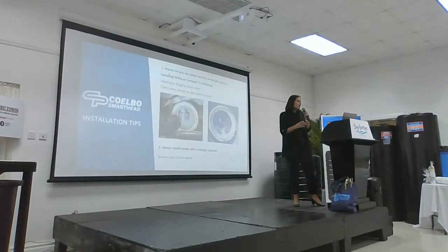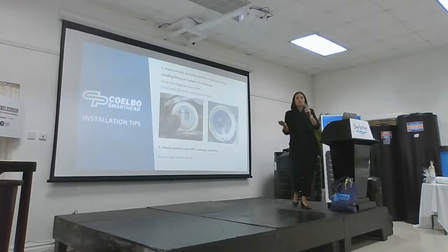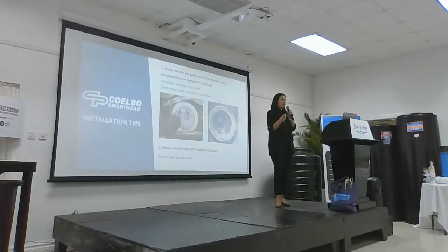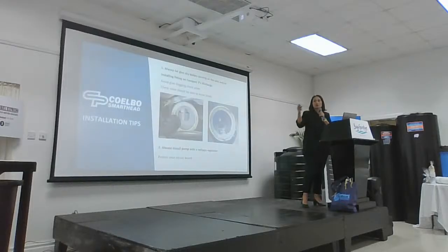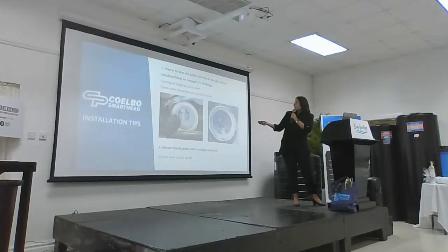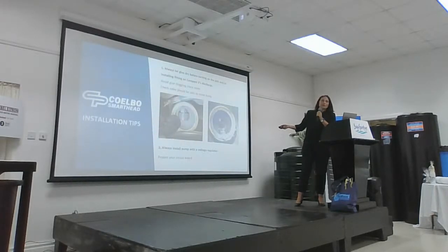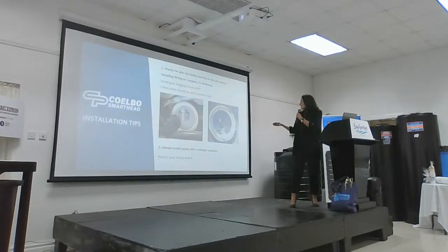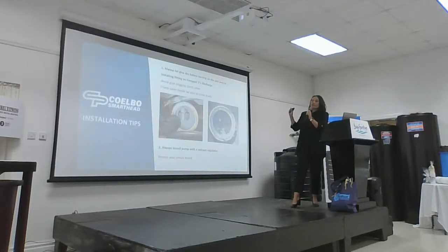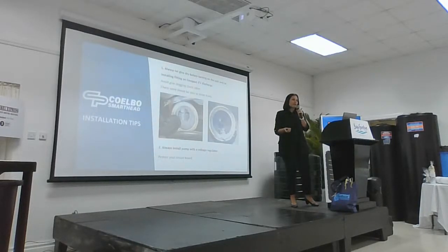So, with installing, sometimes things go awry. For instance, one of the common things that we see is when installing smart heads, too much glue is used, and you don't give it enough time to dry. What happens is that the glue ends up clogging the check valve on the inlet. When you shake the smart head, you should be able to hear the check valve knock back and forth. With too much glue, or glue that hasn't dried properly, it will clog the check valve, and then you'll have to replace the smart head.